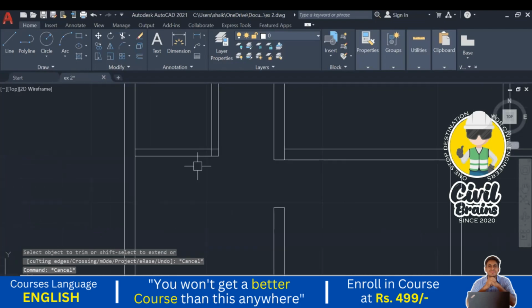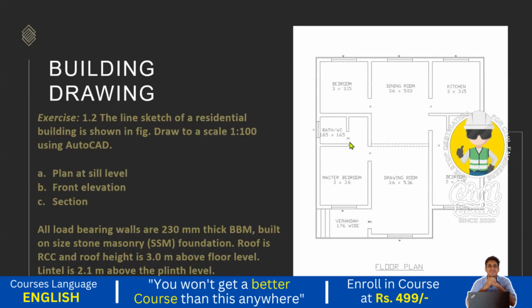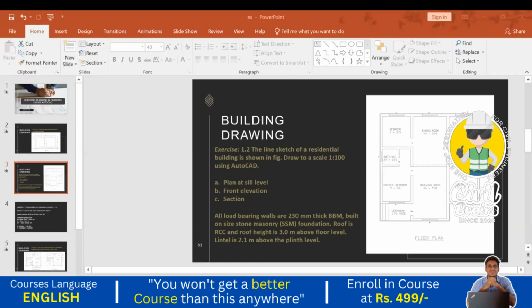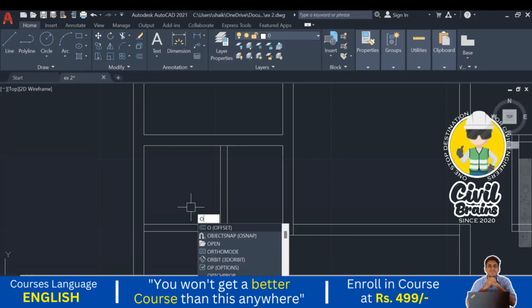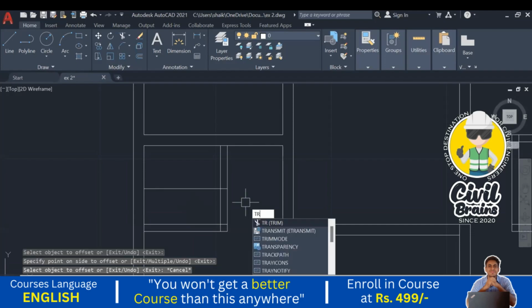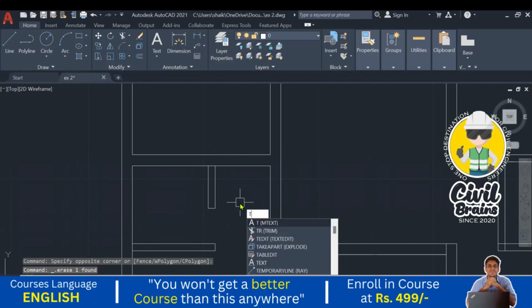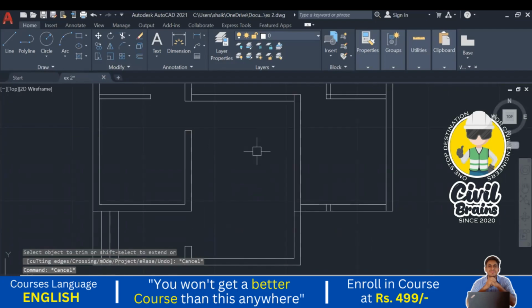Okay, so next the bathroom door, I just check where the bathroom door is. Here it is, from this wall it is 0.75. I just go there, just offset 0.75, enter. Okay, so trim, enter. I just delete this one. Okay, this should look continuous, so I just trim this one. Okay, so this is a line, so it is not a continuous wall.